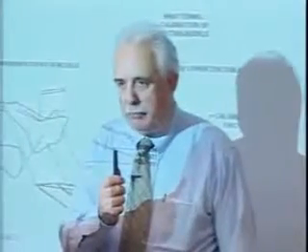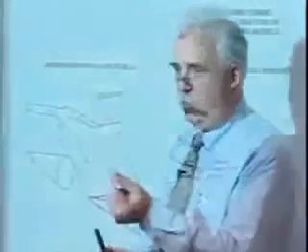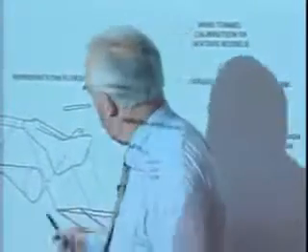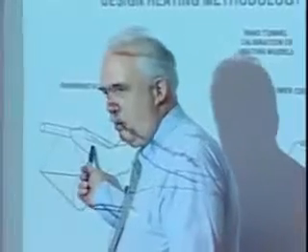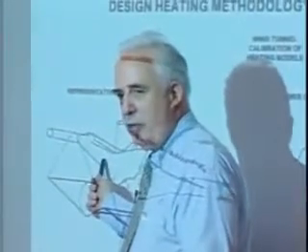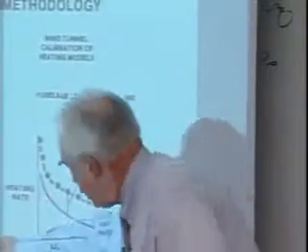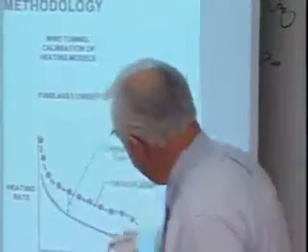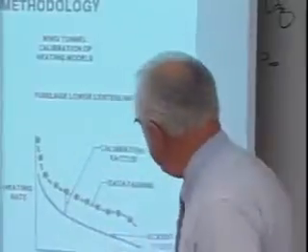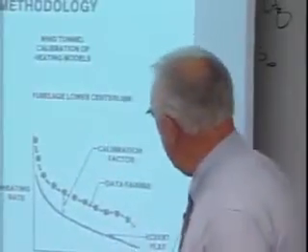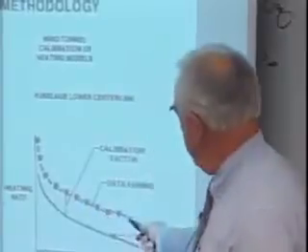These are all one-dimensional flows for the boundary layer, okay? These are flow models, geometric flow models where the boundary layer is basically one-dimensional. And even though, for example, on a cone, the boundary layer is spreading, it's still a one-dimensional flow. So I calculated in the wind tunnel what the heating would be at this particular condition. I calculate, for example, a flat plate. Like this is heating rate as a function of distance from the nose to the tail if you want. Okay, here's what I calculate, here's what I measure.